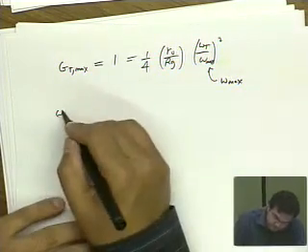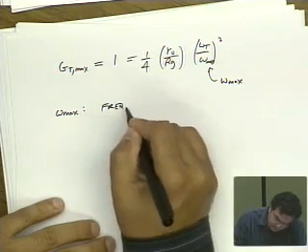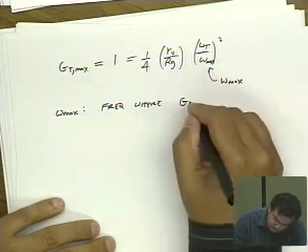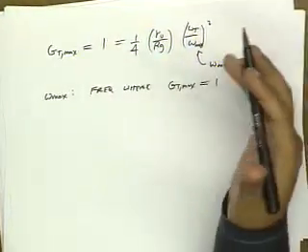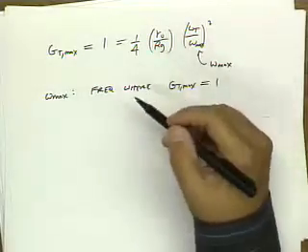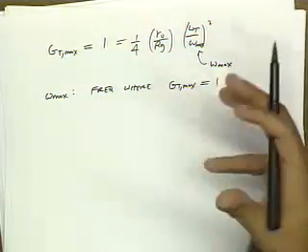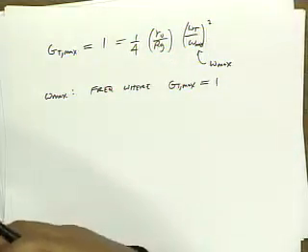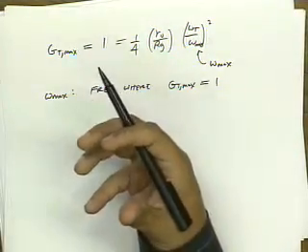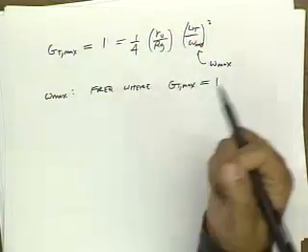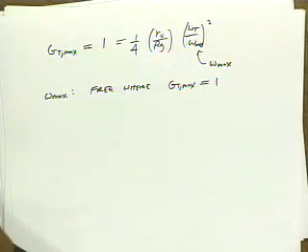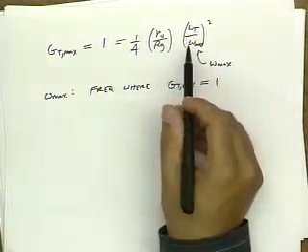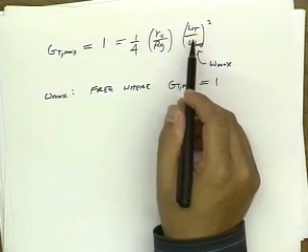So omega max is the frequency where the power gain is equal to 1. And that in some way is a very nice metric. It tells me that if I go beyond this frequency, I can't get power gain from my device. In other words, the whole point of a two-port is to provide power gain. And if you can't get power gain out of your device, it's no longer acting like an active device. It's acting more like a passive device. And so this is a very important frequency. We'll find that it's related to omega t, but it's not equal to omega t.